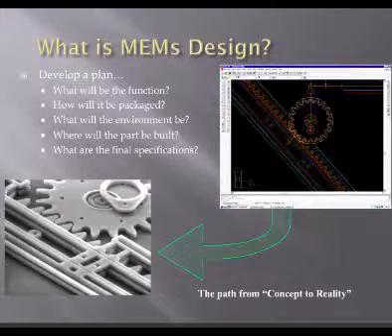The mask set costs $80,000, so you're going to maybe print 8 different designs on one mask set. So it takes a while to collect enough designs that you can make a series of parts for different people. And once you get enough parts together to make the run cost effective, then it takes another 3 months or so to make them.